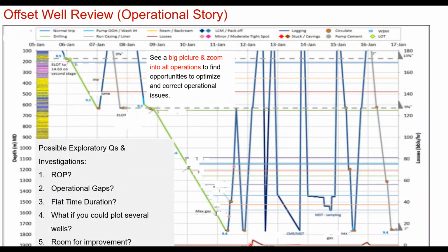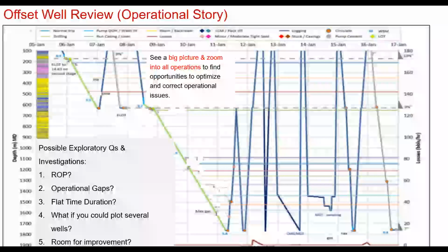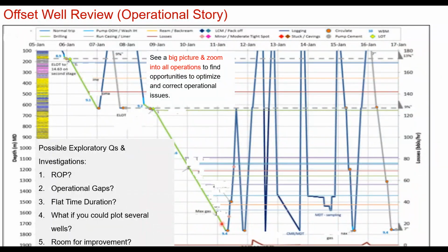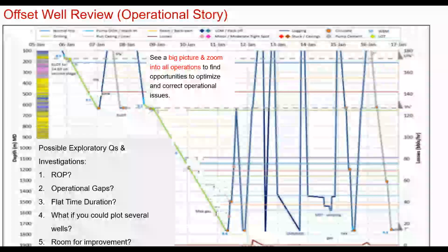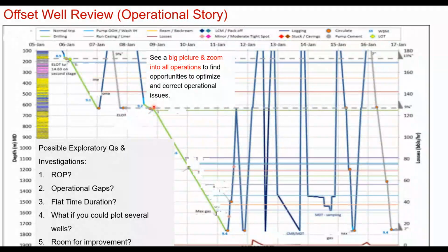And when they pull out of the hole, look at the bit, information about the bit, how badly the bit was actually damaged. It's got high numbers, 3 and 3, cutters are broken and things like that. So now you say, okay, I have done a good job with ROPs for the last section, the green slope, but my bit had been all broken. Maybe I need to improve the bit. If I had a better bit, maybe I could have better ROP, which I did not, which was okay, but it could be even better.